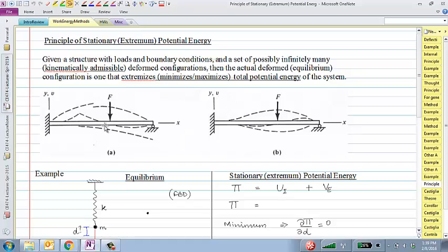So for example here, in this case, this beam curving upwards, going back to displacement 0, even though we know that this won't be the likely deformed shape for a vertical load applied here, this is a kinematically admissible configuration. Similarly, this S-shaped one is also kinematically admissible. And a likely deformed shape, which is this, is also, of course, kinematically admissible. What is not kinematically admissible is this. So maybe I'll write that here: not kinematically admissible. And the figure on the right is admissible.